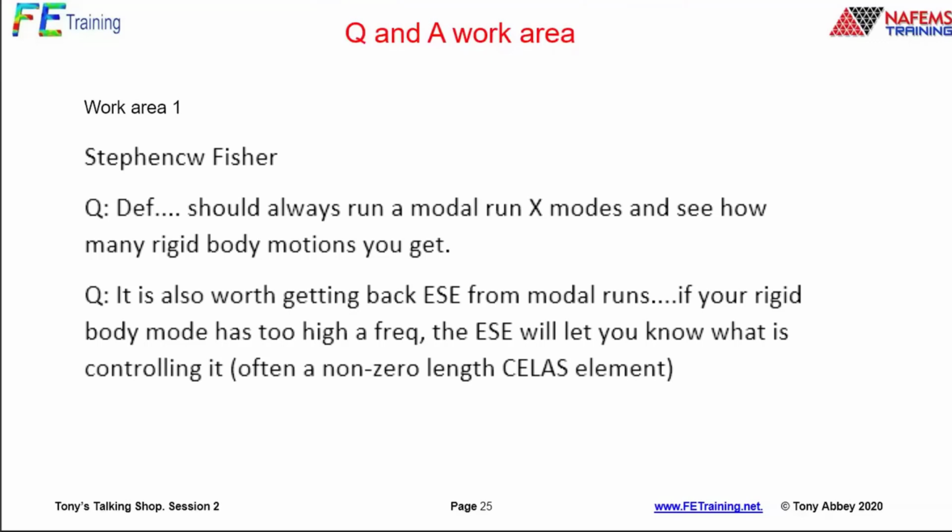Anything really in this category is anything that's going to head off errors fast. You're going to pick it up fast. If you can spot that, again, a good idea. I could even add to this, there's an element strain energy check in our normal static analysis, sometimes called an epsilon check, sometimes an energy norm check. It's described in different ways. That value should be very small. If it's an epsilon designation, it should be 1e-9 or smaller. If you can spot that quick, which I tend to do because I'm diving into the text file, then so much the better.